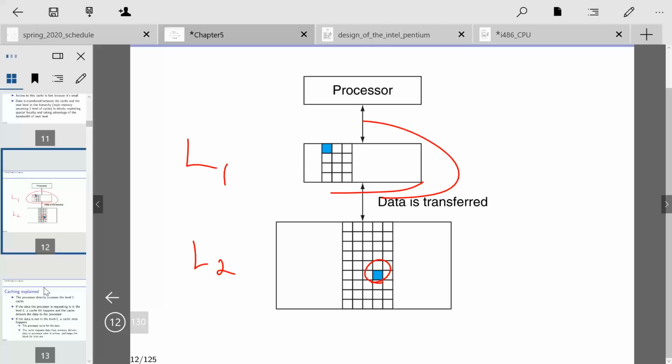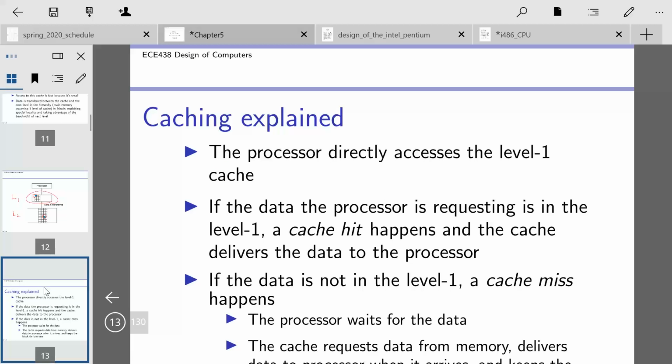Now, if this was main memory, then there would be a special path that allows the processor to directly access main memory uncached for certain corner case situations, like memory mapped I/O. You don't cache memory mapped I/O. The processor directly writes to the peripherals through that memory map. But so those I/O devices live in the section of uncached kernel space.